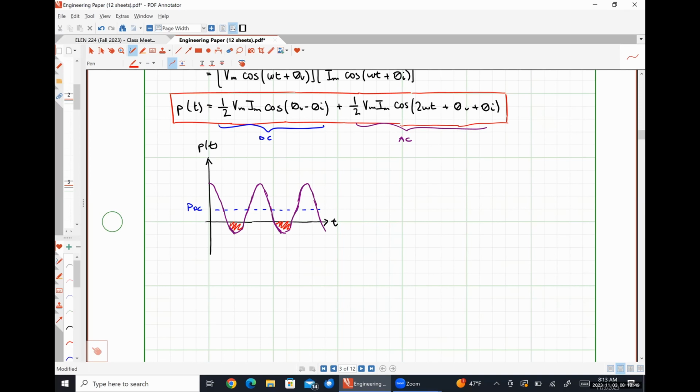So this particular wave shape is characteristic of a circuit that contains energy storage elements, right? So capacitors and or inductors, okay? Anytime we have any energy storage elements in our steady state sinusoidal system, we will see that sometimes the energy stored by those elements gets to supply power back to the source. And we'll talk about this phenomenon significantly more over our next two class meetings as we investigate the concept of power factor in a steady state sinusoidal system. Okay. I just wanted to point that out to you guys because it's interesting.